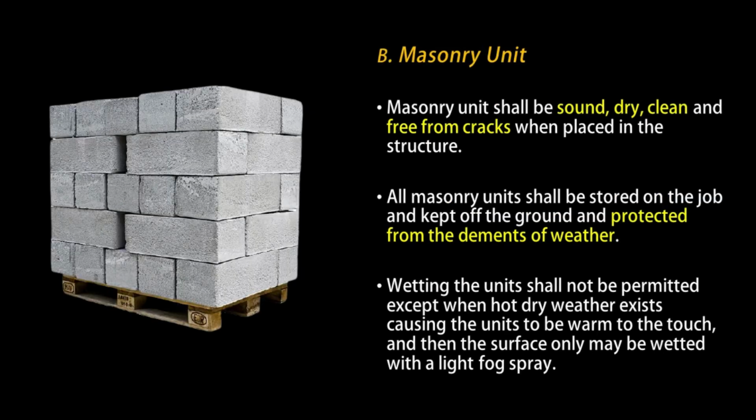Masonry Unit. Masonry units shall be sound, dry, clean, and free from cracks when placed in the structure. All masonry units shall be stored on the job and kept off the ground and protected from the elements of weather. Wetting the units shall not be permitted except when hot, dry weather exists causing the units to be warm to touch, and then the surface may only be wetted with a light fog spray.